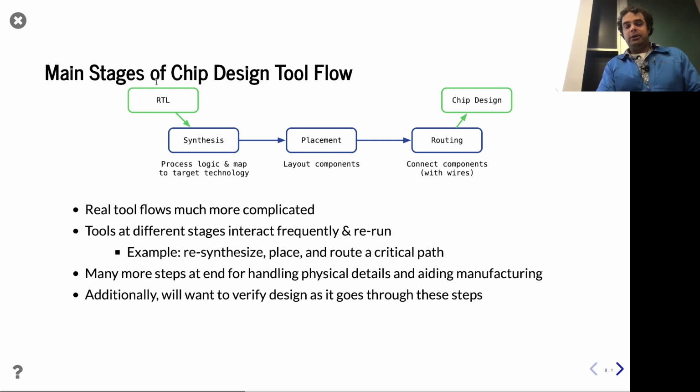Well, you need to turn that Verilog into actual hardware components, various logic gates and adders, registers, whatever. That's synthesis. Of course, these aren't just random logic gates. These are logic gates or components inside of whatever implementation technology you're targeting, perhaps a certain ASIC flow or perhaps a certain FPGA. And you place those things out in 2 dimensions, perhaps soon in 3 dimensions, but for now, 2D. Lay those things out.